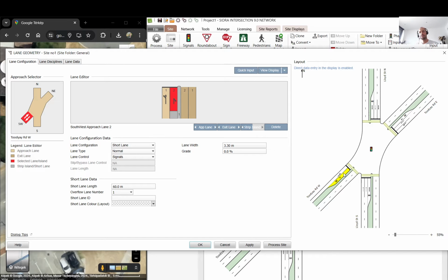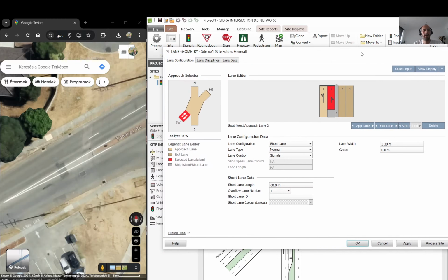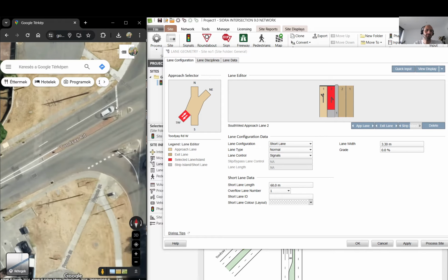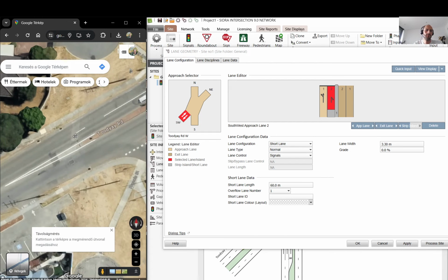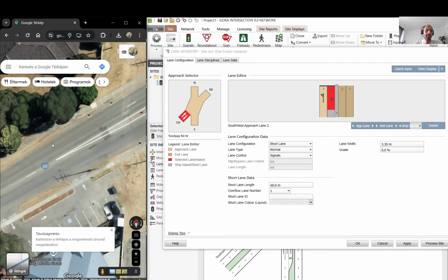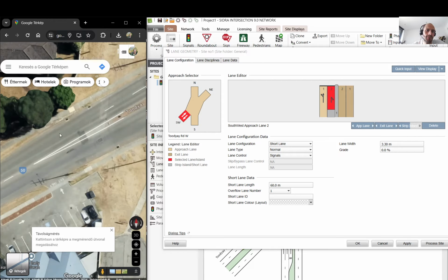You can have a look at some survey videos if you ever go on site to see how vehicles queue. But I think you just need to select one way when it's not that obvious, and you need to measure the distance. How long is that single lane? So what I try to do is where vehicles can diverge into a lane or where they can be next to each other, basically. So I think it's approximately here, so it's around 40 meters.